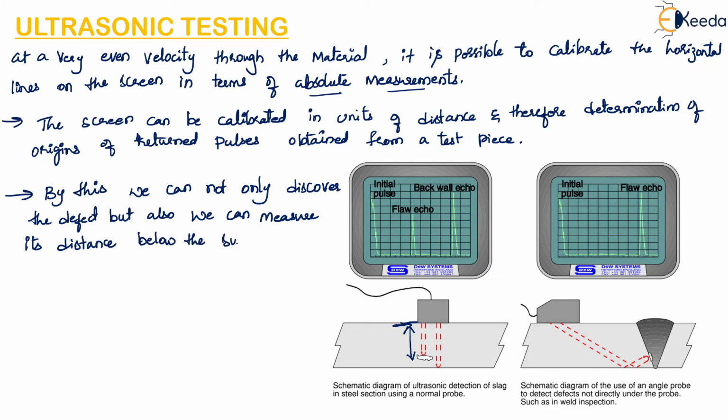below the surface. So it is important that the equipment is properly calibrated, and since it is not in itself able to discriminate between the intended boundaries of the object under test and unintended discontinuities, the operator must be able to identify the origin of the peaks.